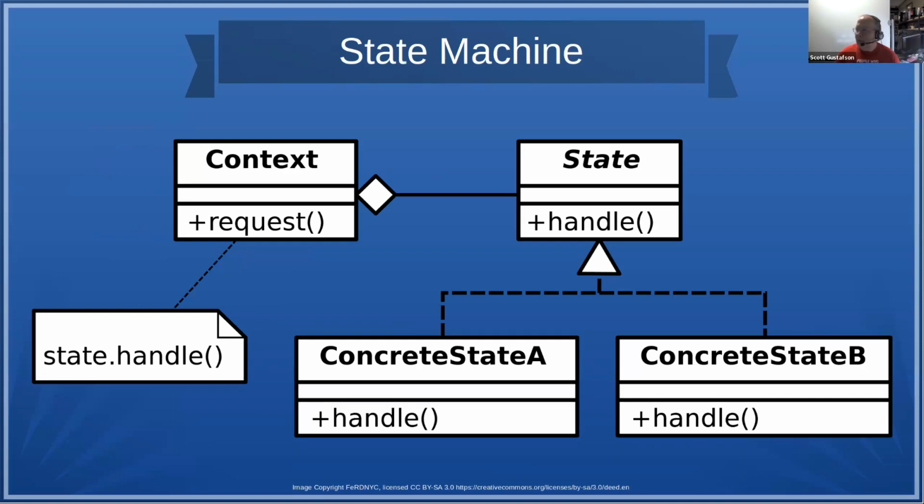Because when I think of a stoplight, I think of a state machine. Because I can't have both the red and the green on, for example. So those are two independent states. And I need to be able to say, hey, you're either in the red state or you're in the green state, or say you're in the yellow state, or hey, the walk sign is on, or the don't walk sign is on, or some other thing.